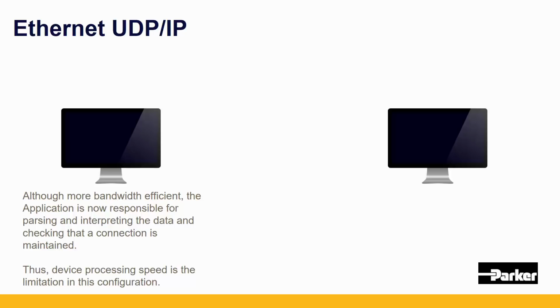All of a sudden, processing speed becomes very, very important. Because right now we have a single connection from 2 devices, but imagine if I have 50 slave devices on my network. The processor speed of the master not only determines how many slave devices that you can connect up to, but it also determines how quickly you can communicate to each one of those slave devices. So again, kind of bringing this back to the Allen Bradley realm, it really is kind of your difference between your regular scanner and your ultra high precision scanner.